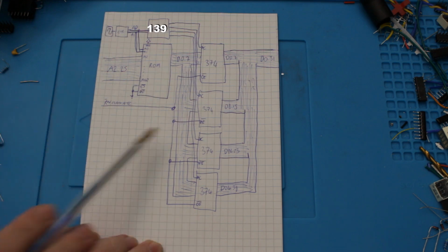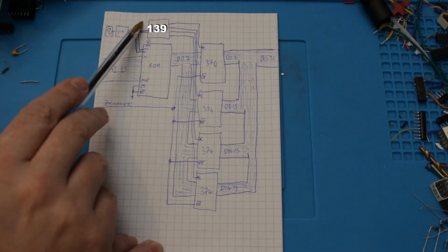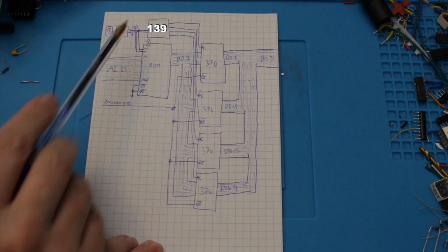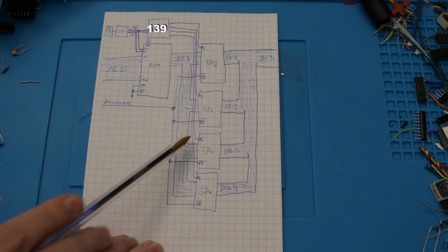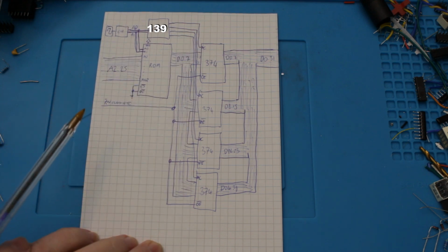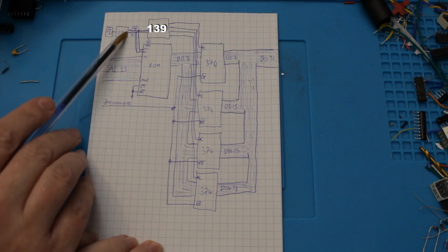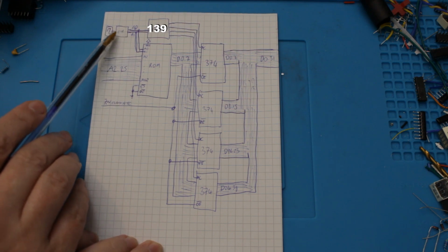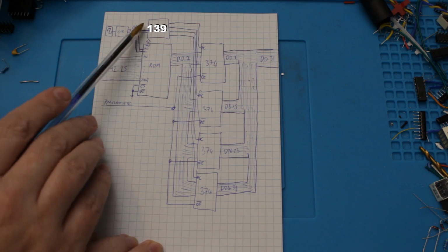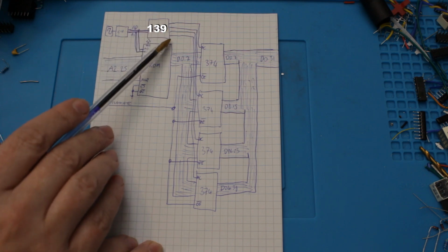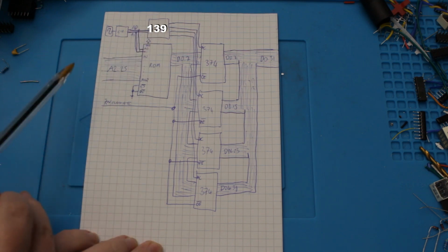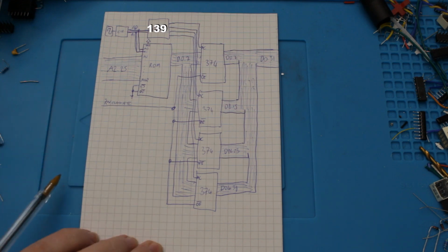Some of the details I haven't nailed down here are exactly when we enable and disable this 137, because that will also cause some element of ticking to happen. We might need to count more than 4 here. We might want to count to 8 so that there's a bit of clear space between each of the outputs going high. We never have 2 high at the same time. I haven't figured out all the timing for that yet.